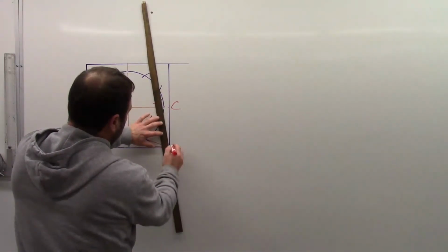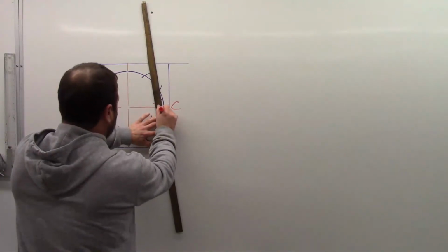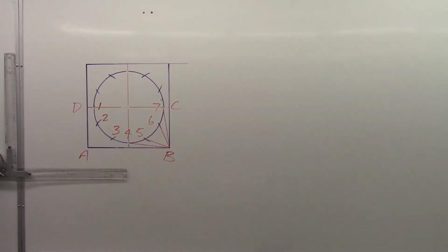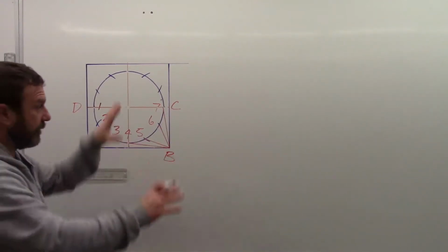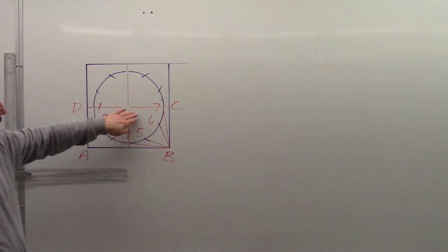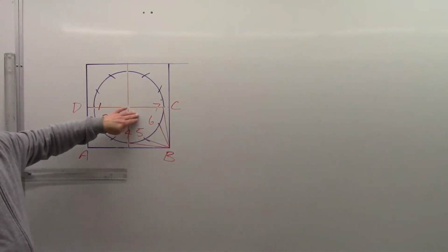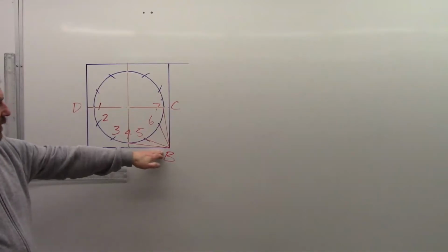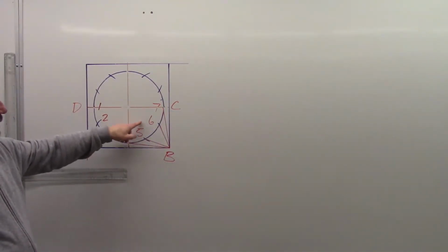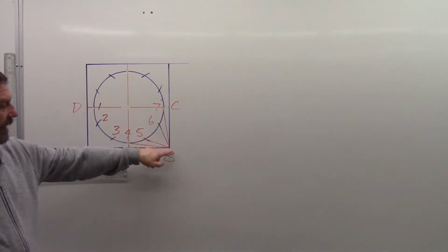And what I'm doing, and this goes for any square to round, is that it doesn't matter where the two ends are. They can be all over the place. We're going to take one quadrant of the circle and connect it to a corner of one quarter of the square. So the lower right in this case all connects to the lower right.